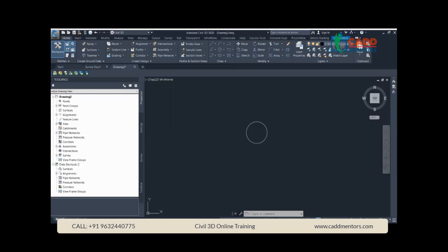And when it comes to Export, let us say you design something. I think some of you are familiar with AutoCAD. Generally, once a designer has done something, in order to put it in the viewports, print it on paper and submit it to the client, the Civil 3D files are exported as an AutoCAD drawing and given to the CAD technicians, the draftsmen, to put into the actual layout system. They work on legends and everything, and make it on paper. So in order to give it to them, we use Export very frequently, either as a DWG format, exported as a Civil 3D drawing, or sometimes, if required, we deliver in other formats as well.